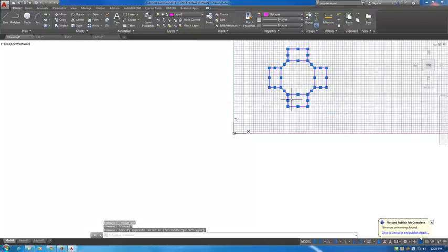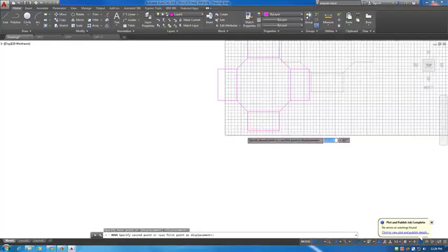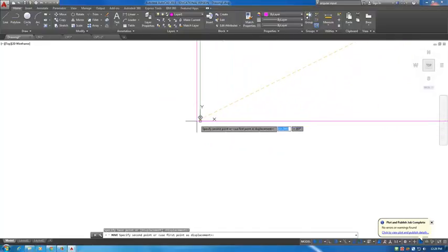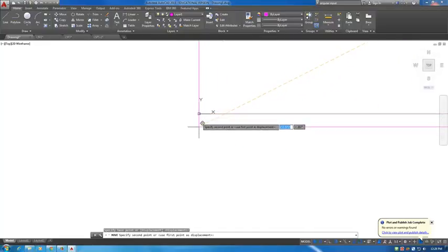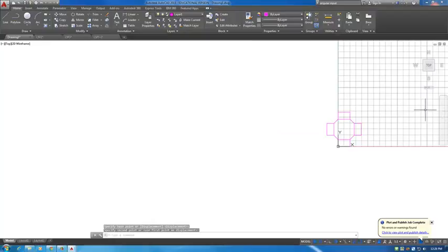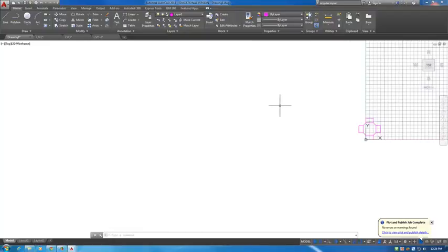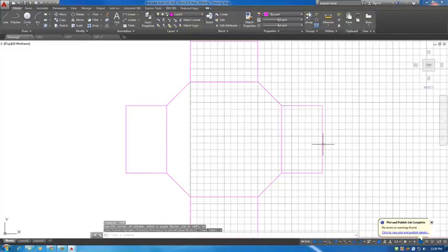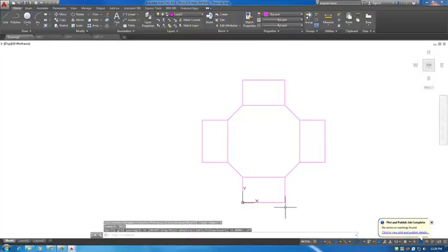So I'm going to select my object here, right click, move, select my base point, zoom way in down here. Okay, see how it goes right to the origin, snaps right to the origin. Okay, that's an easy way to do it. That's the easiest way I've found to do it. And then we can actually zoom, E for extents, brings our drawing, type in grid, off, turns the grid off, and that point that I specified was right on the origin, so that is at 0, 0.